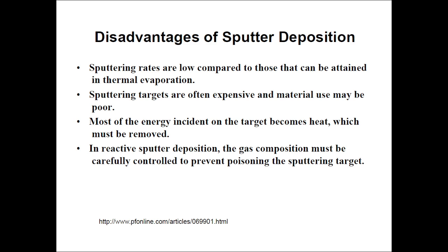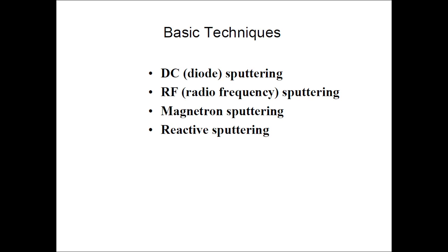Most of the energy at the target becomes heat which must be removed, and in reactive sputter deposition the gas composition must be carefully controlled to prevent poisoning of the sputtering target.